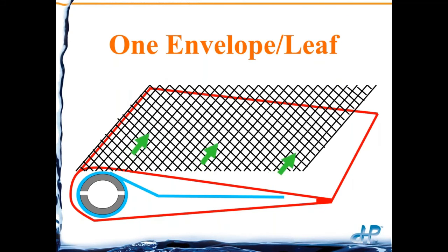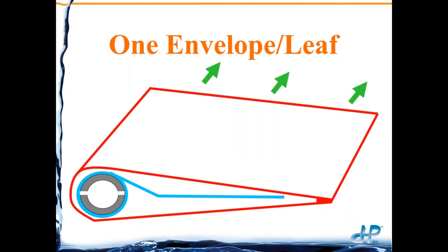That water comes in and goes through, exits out the concentrate, due to the pressure from either the high pressure pump or the city. The water passes through the membrane, gets into the permeate water carrier, goes through those channels down to our permeate tube, and then exits out whichever end is easiest for the plumbing or the piping coming out of the RO